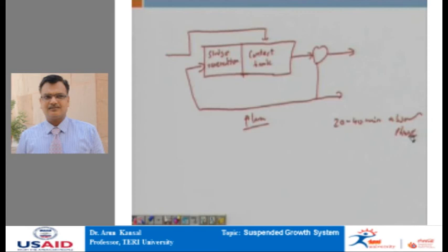During this phase, most of the colloidal, finely suspended and dissolved organics are absorbed in the activated sludge. The second phase, which is the oxidation phase, occurs and the absorbed organics are assimilated metabolically. So, if you recall, we have adsorption, absorption, and assimilation, dissimilation.